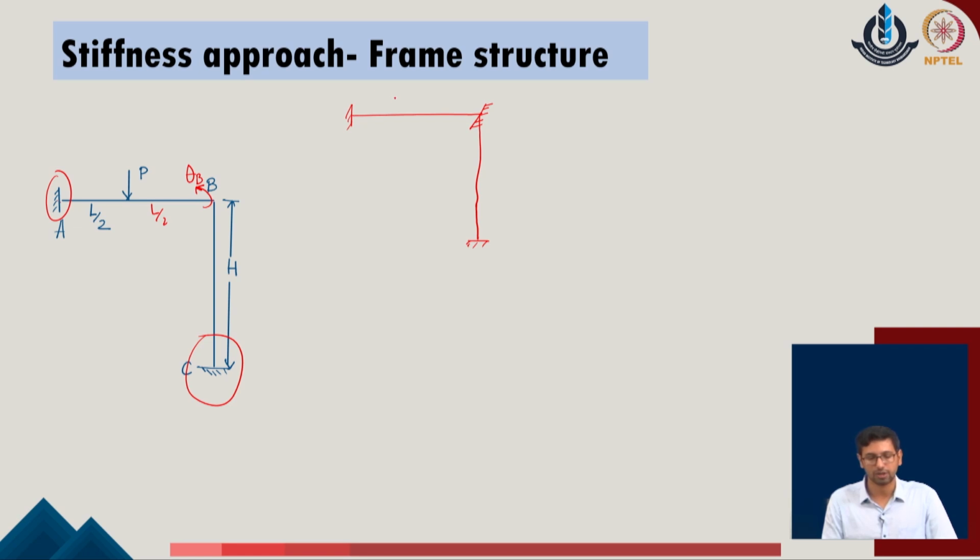With respect to the external load which is applied, we can calculate the fixed end reactions. So, this value will come out as P by 2. The reaction over here will also be P by 2, which I can directly translate to this point. The net moment which will appear here will be PL upon 8, and over here it is also PL upon 8 for the given system. We have taken these values from the standard results which we generated in the force method. One can go back to those discussions and get these results for the standard fixed end systems.